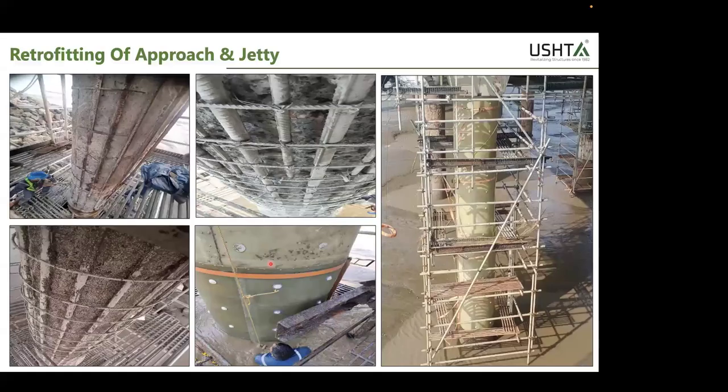So you fix up this jacket, and you start grouting from below. By pressure, you pump in underwater curable epoxy paste, which is grouted at a very high pressure. We grout almost at 5000 bars. What it does is it displaces the water, displaces the cavity and fully jackets that entire portion. It makes the concrete absolutely inert. It protects the concrete, and secondly, when you push the epoxy paste at such high pressure, you are actually creating some pre-stressing effect on the jacket. So my jacket from day one becomes active.